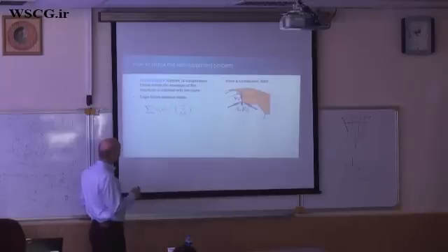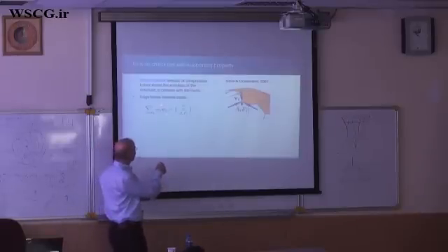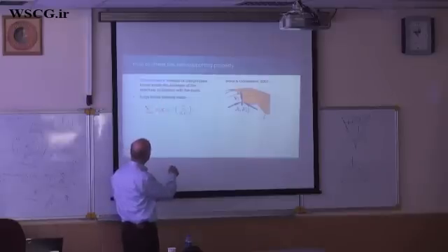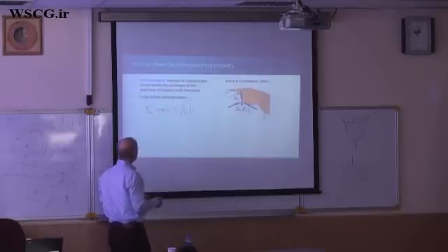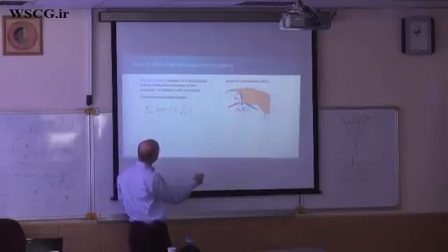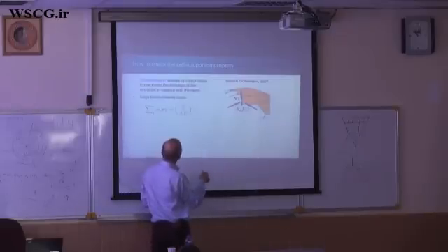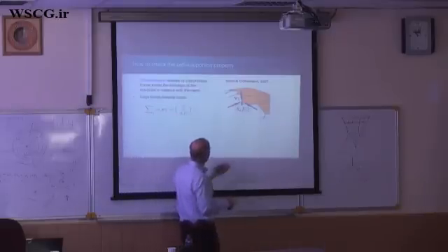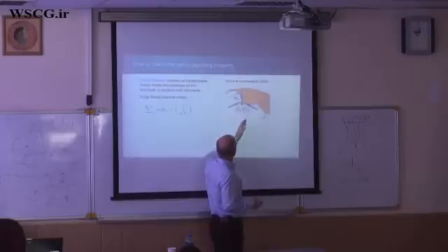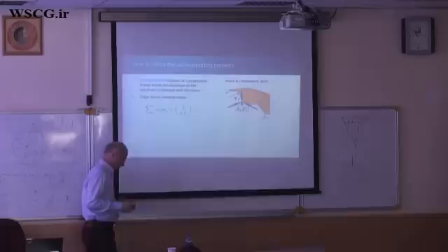So this is an edge vector. Eij is the vector from vertex Vi to vertex Vj. And this Wij is the force density. And so this is the force acting in an edge. And along each vertex Vi, all incoming edges have to balance the weight, which is usually vertical, because we only consider here the self-weight.